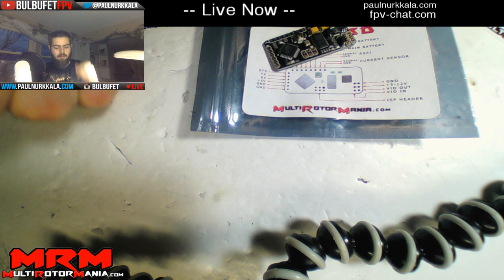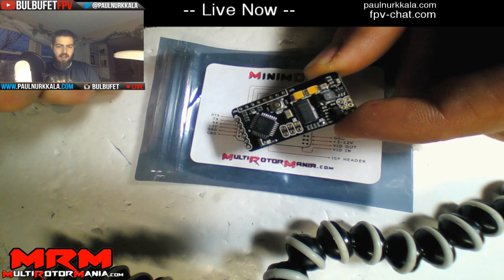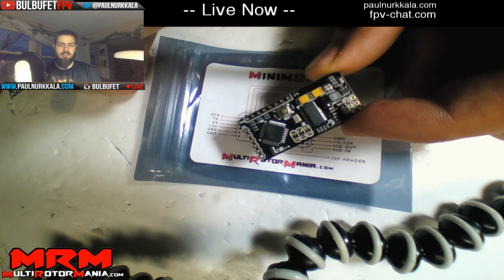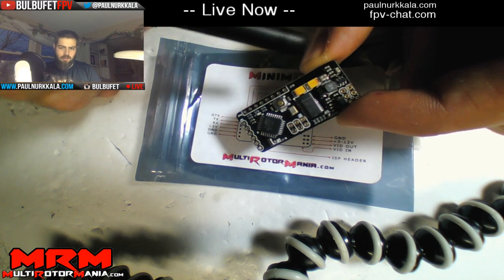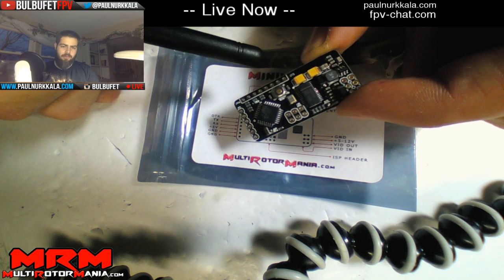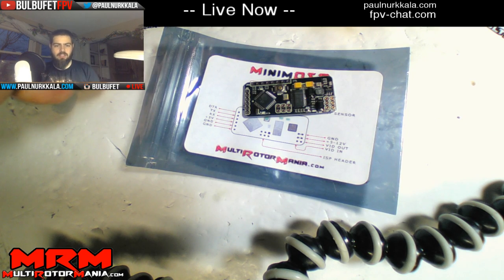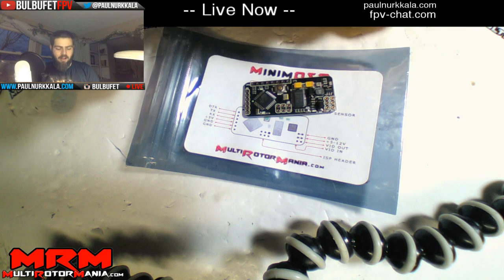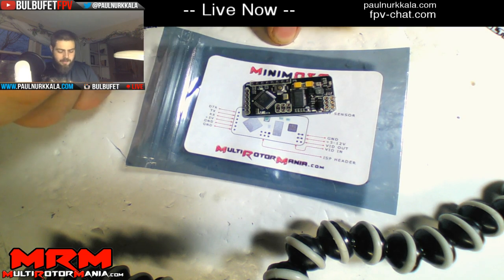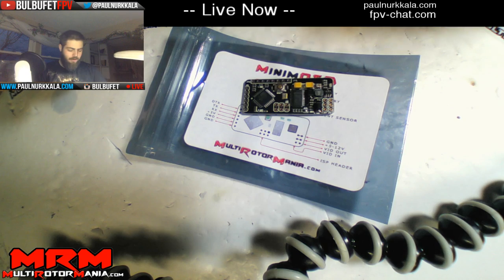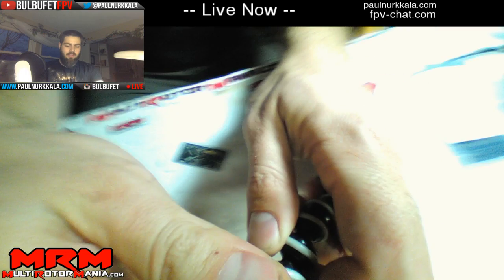So basically what's happening is that this guy here is sitting between your camera and your VTX, and it processes in between, takes all of the variables that we're going to configure, puts it onto that video feed, and then sends it out through the VTX back to your goggles. So it's kind of doing a bunch of calculations on the fly on the board between you and the goggles, not adding any latency at all. So that's what we've got. This is what we're going to be working on mostly, the MRM OSD.